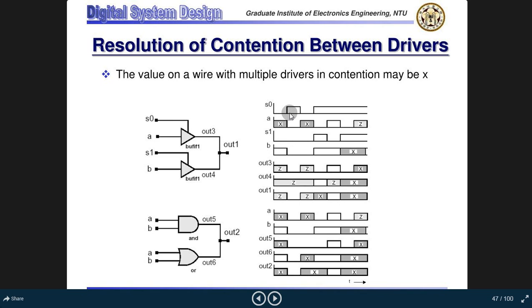Okay, so now suppose the value of S0 is 1. So we will get a 0 value. The same here. Now suppose we have a value of 1 here at S0, so depending upon the output, suppose this is the A, so it will be propagated. The same will be applicable for high impedance and X. Now for high impedance and the unambiguous value, for unambiguous value input we will get a high impedance output. For high impedance input we get an unambiguous output.